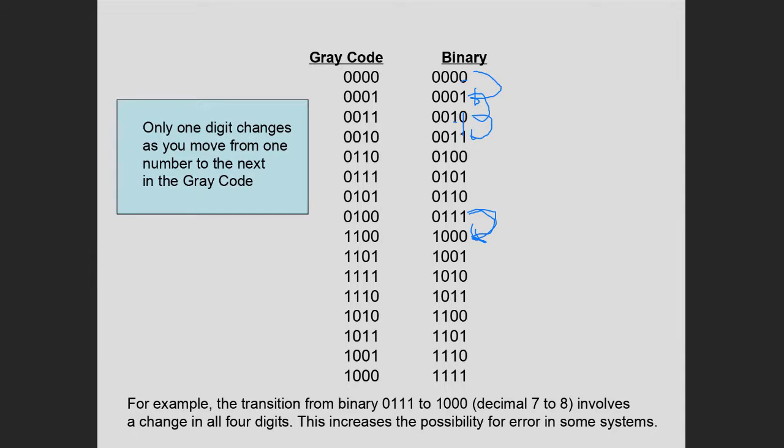So with gray code, if you code a binary number, or say alphanumeric data, in gray code, as you go down, you'll notice only 1 bit changes at a time. Even down here in binary, when I went from a 7 base 2 to an 8 base 2, I had to change 4 bits.